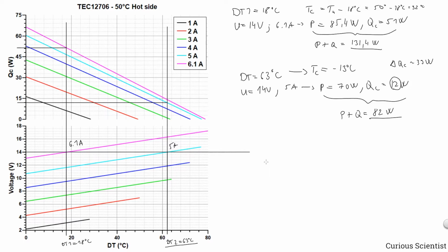The reason why they can measure, or I also can measure, very low temperatures on the cold side is because there are no objects attached to the cold side of the Peltier cooler, which means that the Peltier cooler doesn't have to transfer too much heat from anywhere. Because A, there are no things attached to it, or there are no heat sources. B, the contact between the surrounding air and the cold side of the Peltier cooler, even when it is exposed, is not that good.